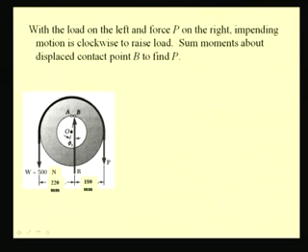That means this pulley tends to move in the clockwise direction over the axle or the shaft. So, the point of contact, which is originally at A, now shifts to B, and it tends to slip at this point B.